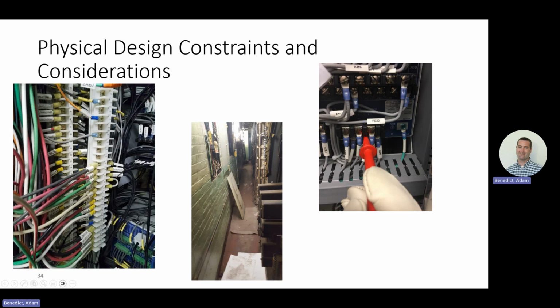Looking at some of these, you see this panel is clearly loaded, where you have terminal block here. This is the standoff terminal block. So you have wires on top of wires. It's not ideal at all. So if you can avoid situations like this, and this is where site visits at kickoff can help alleviate some of this, where you can identify better places to install relays, protection, controls, and avoid trying to double up on terminal blocks.